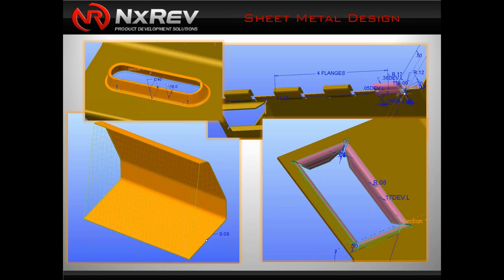Talked about how we took a solid piece of geometry and turned it into a piece of sheet metal. We then saw copy and doing a paste special to create a feature that had intelligence, so that if one was updated, they all were. We did a rectangular cutout and added some corner reliefs. Saw the flat pattern display, as well as talked about how to create a flattened instance.